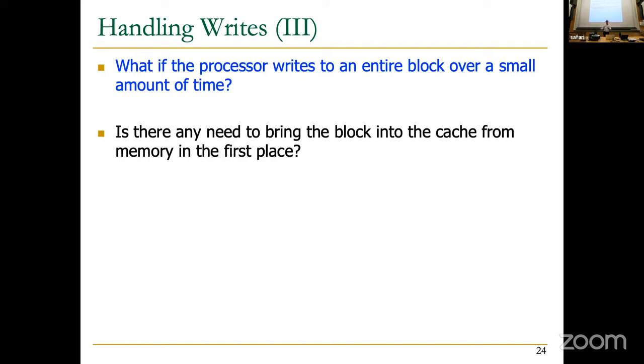Today, as we discussed, the cache block granularity is 64 bytes. Write granularity, store word, as you've seen, is 4 bytes, right? Or 8 bytes, let's say. You can have 8-byte stores also. That's much smaller than the cache block granularity. So how do you implement this?